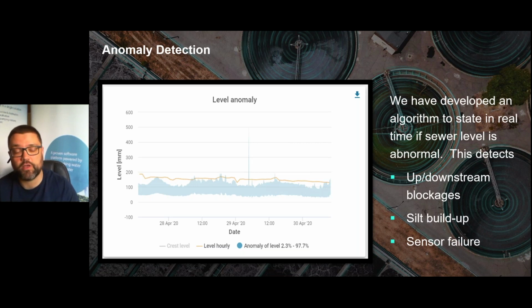And that's where we really do think the benefit to water utilities will come from. If you can recognize that your sewer level, your CSO level, or even just your network monitoring level is incorrect, and you can recognize that you've got a certain time period, you can get out and clear that. You can deploy a jetting team. It may be a symptom of a failing sewer further downstream. It might mean that one of your pipes has started to bow or started to break. You can get out and you can solve those problems before it becomes a blockage. And that's the real key.